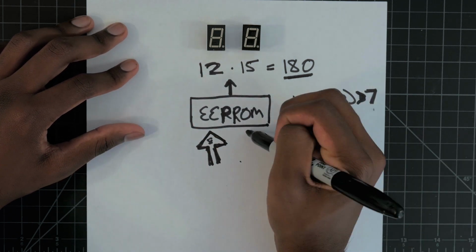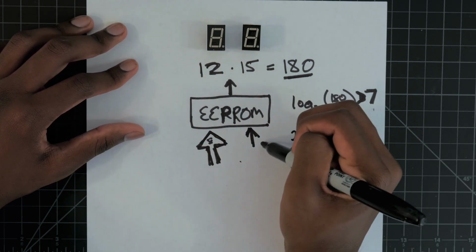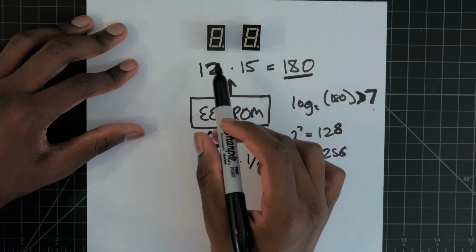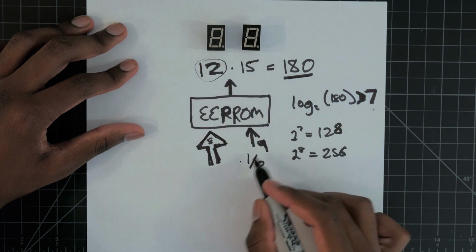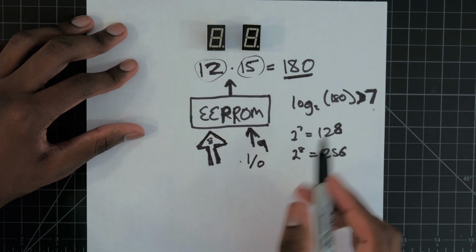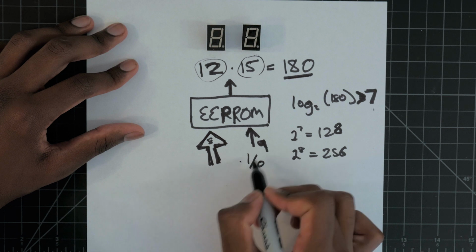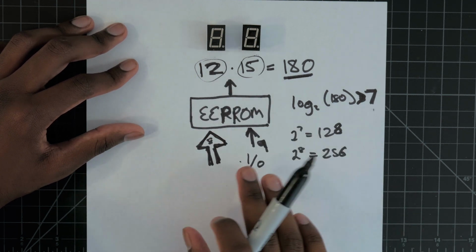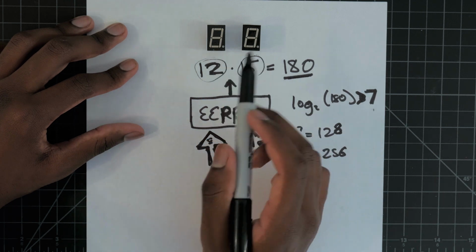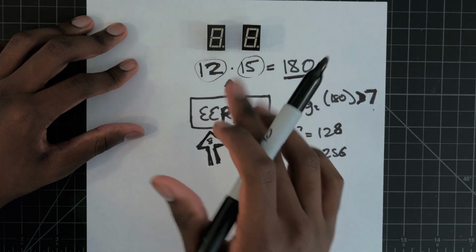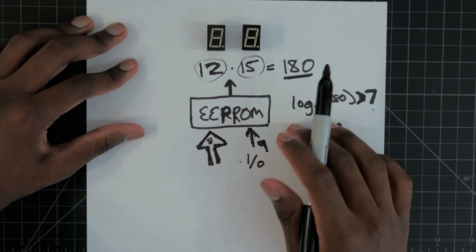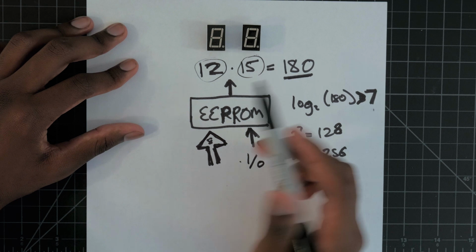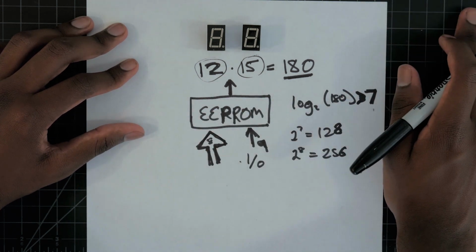So what we can do is use a 9th bit to drive the EEPROM, and this will tell it either 1 or 0, where 1 might correspond to the hours digit and 0 might correspond to the minutes digit. It will just say, take the time, and if it's a 1, output the hours, and if it's a 0, output the minutes, and we'll flash through these really quickly so that the value on the displays changes really quickly, and people really won't be able to tell that we're only displaying one number at a time. It'll just look like we're displaying both of them.